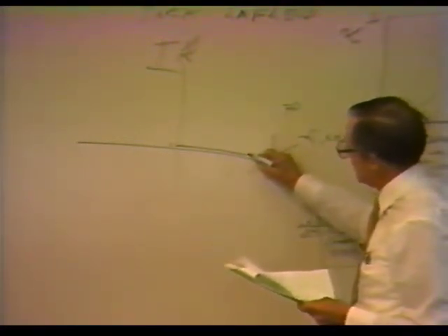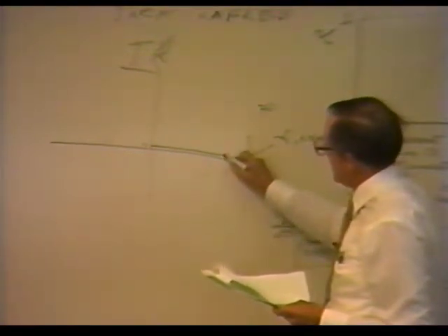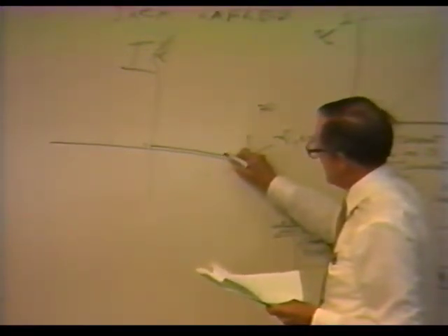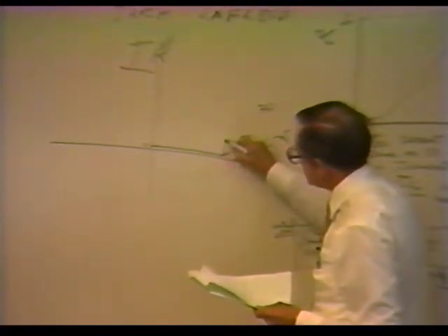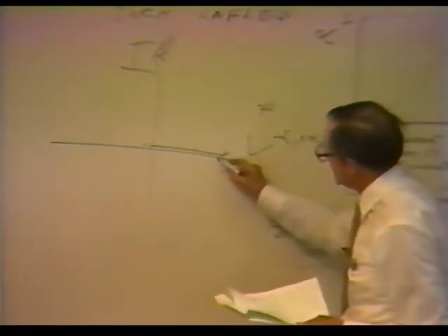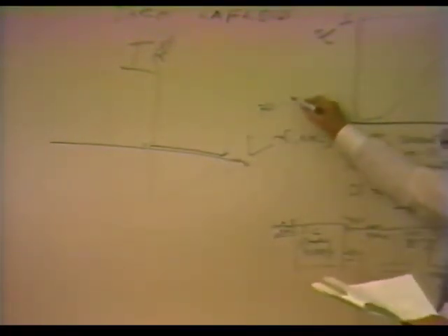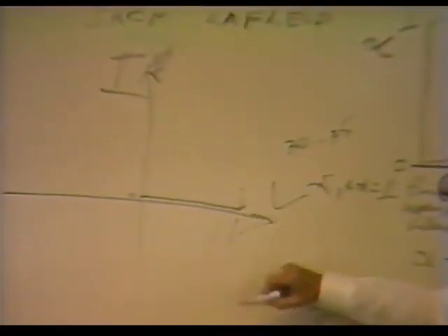So when I can no longer apply the anode voltage and have it extend, it starts conducting current because we're getting into avalanche. And I crank more and more voltage into that. I go to 35 volts, but 35 volts don't come out. It still pegs here at 30 volts.